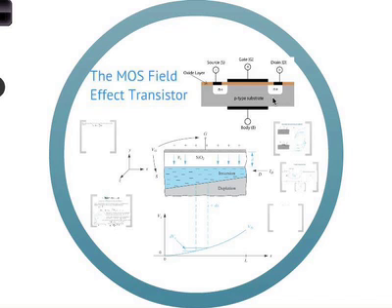And you have a gate voltage which controls the channel between the source and the drain. The input voltage comes across the source and the drain, the output current is the current between the source and the drain, and the control is at the gate. Typically the drain and the body are connected together, and we'll come back to that. That turns out to be an important point.